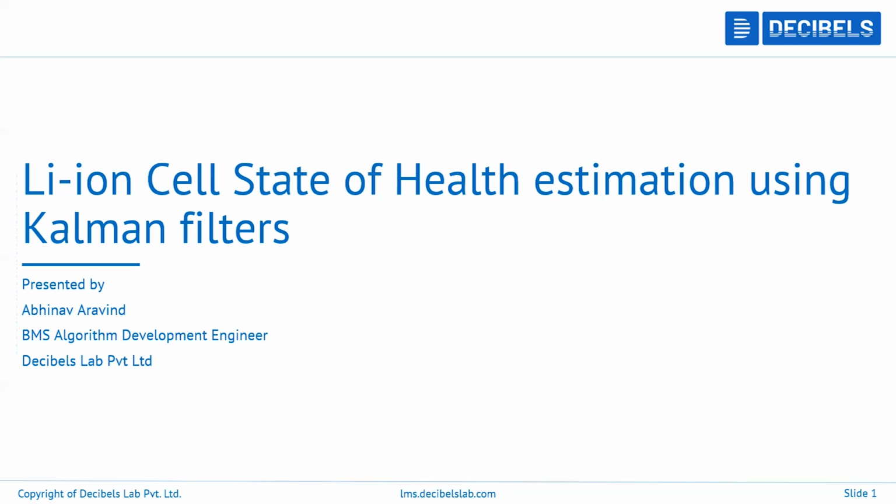Kalman filters. Kalman filters are one of the most widely used estimation algorithms in today's EV market. It is one of the most sophisticated estimation methods, which promises really good results. We'll see in this webinar exactly how we can use the Kalman filters. We'll also have a quick overview of the model. There is a Matlab Simulink model prepared here, and we'll have a quick overview of that along with the necessary algorithm.